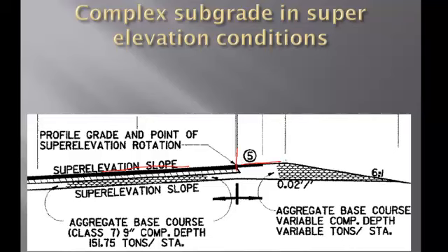There is also calculations provided by the state. It's usually an algebraic breakover that allows the foreslope here to not exceed a certain percentage difference from the super elevated slope. These are often outlined in tables off to the side on the details pages, or they're just part of the state standard details. So you've got to pay particular attention when building the finish road, and then once that is done, now it's time to do the subgrade. Again, another model has to be produced and another set of calculations has to be run.